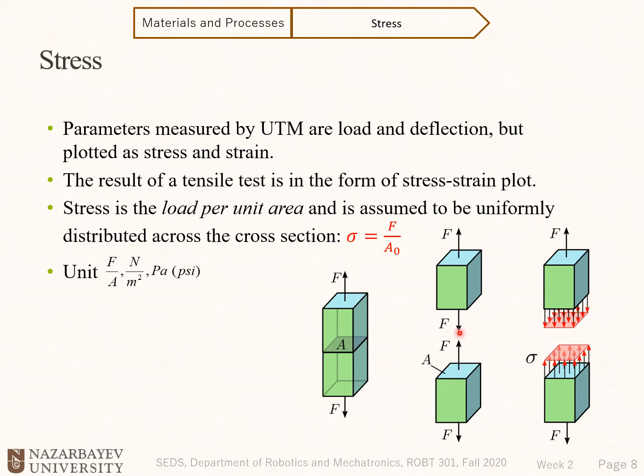But do we really have a concentrated force at this cross section? No. This force is basically a resultant force, but it is not the actual force. What's happening in the cross section is that we have a distributed force, or stress, of sigma.